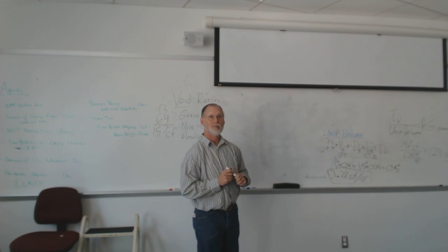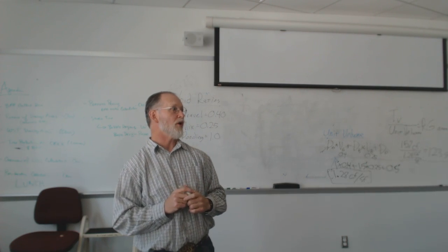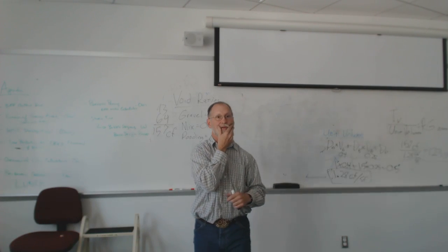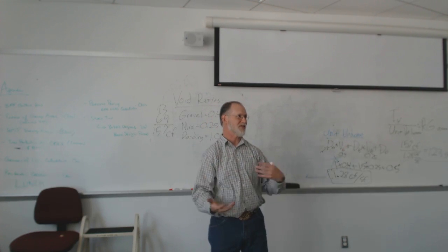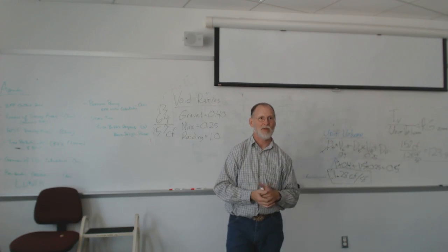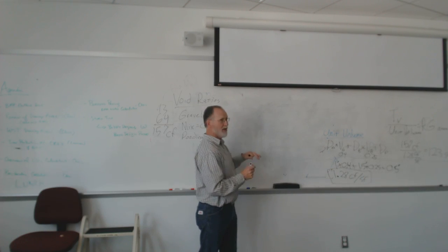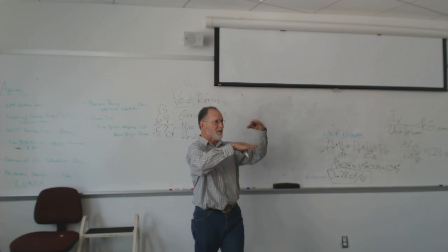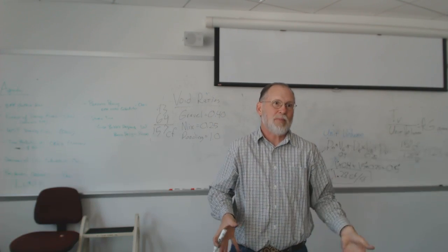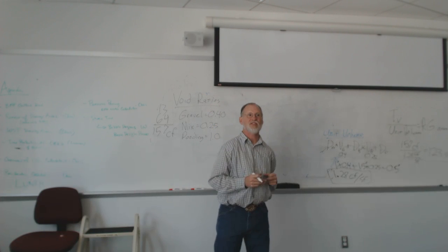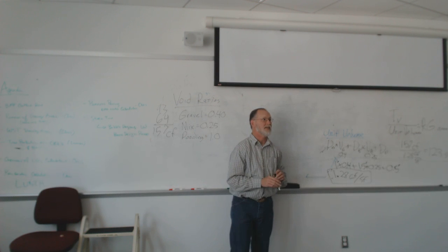So in the 18-inch minimum, you just account for the root requirements. Right, you want to provide root requirements. You also want to deal with what Alex had mentioned before. You want to have some buffer in there so as all these pollutants are coming in, your soils aren't getting saturated, and your plants have something to eat and drink. Because that gravel layer is dry, basically. So if you just have a thin little amount of bioretention mix on a big gravel layer, it's basically hitting the air at that point. It's not getting what it's going to need for a plant.